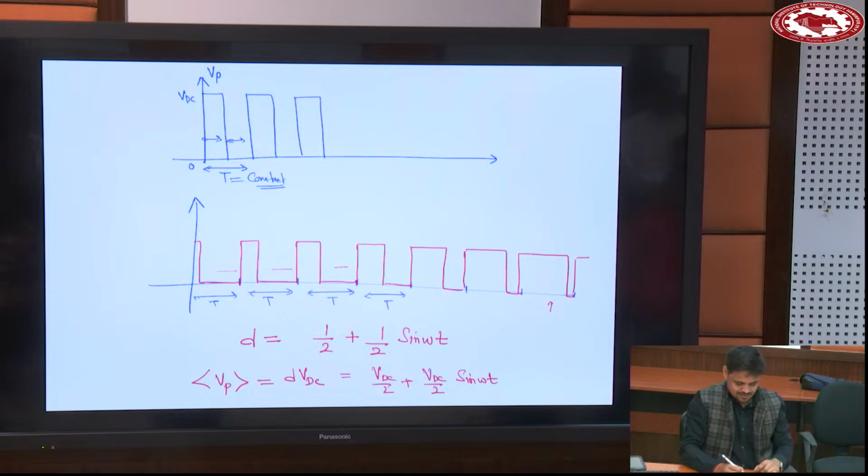By the way, this method of PWM generation is known as sine PWM. Why sine PWM? Because the turn on time of the switch is modulated sinusoidally. Small, then increasing, then increasing, then increasing, becoming high. Getting my point?